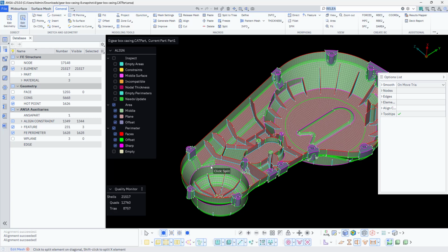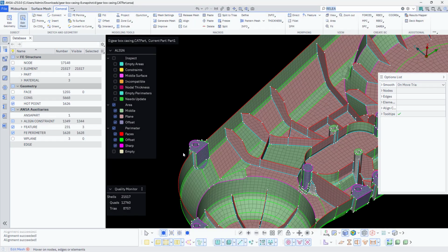And now finally what you need to do is you need to assign the thickness to the PIDs for this entire mesh considering the CAD. So how do we do that? By just measuring the thickness of the CAD and then just selecting the ribs and the shell regions, mount regions, and define the thickness. Okay, so this is what we're going to do in the session now. Okay, let's just do that.